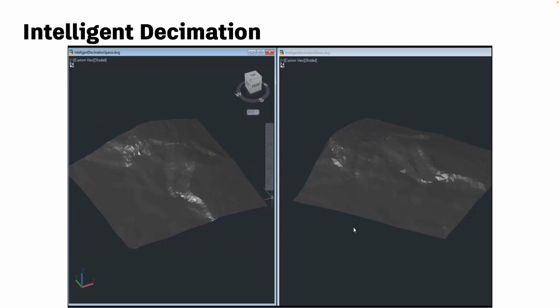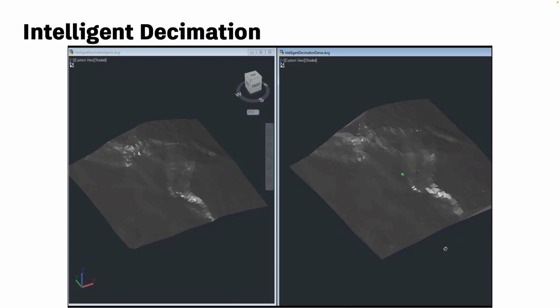We did the volumetric calculation and all those things to check how different it is. But at the end of the day, you can get the exact surface you would get from all the points with the decimated points, without losing accuracy. And now you have fewer points, which means fewer triangles, which means you have a better surface in your Civil 3D model. Now you marry this with the step 3 results of the feature lines and the assets.